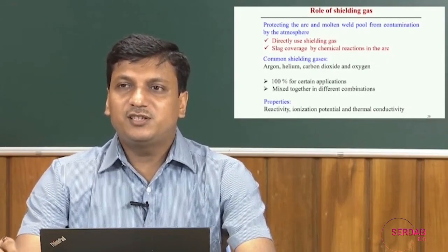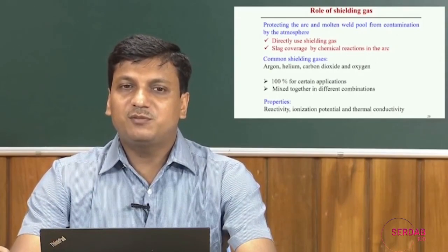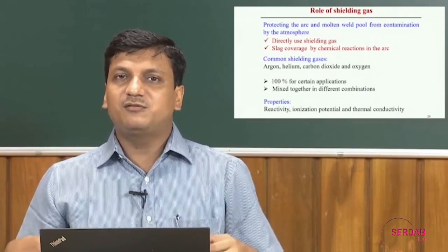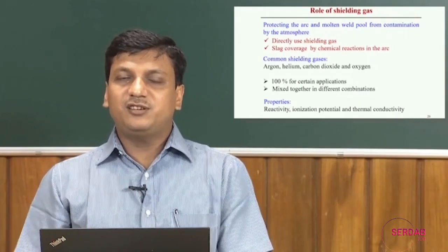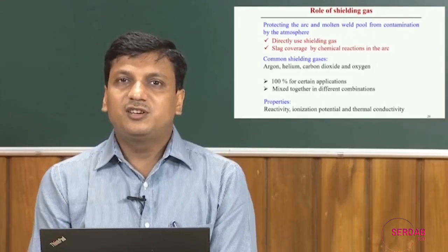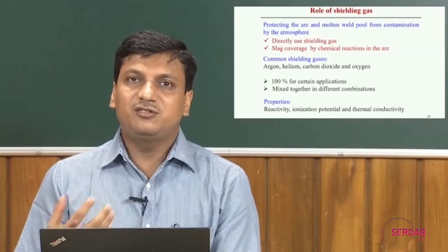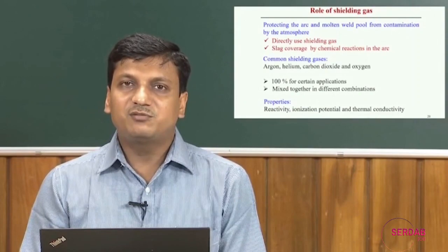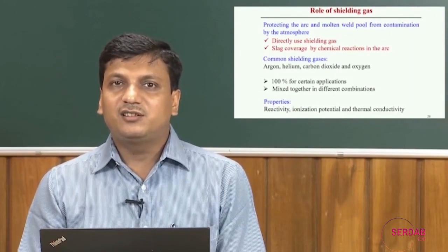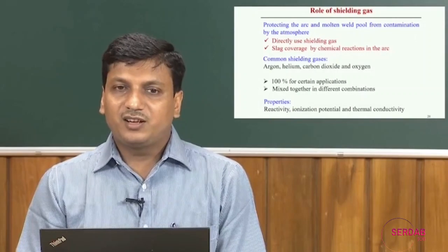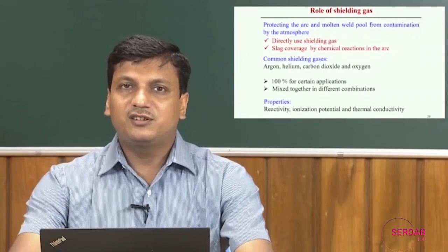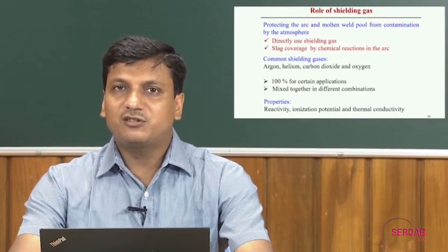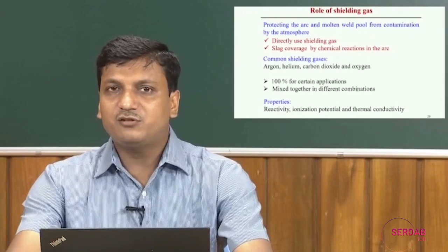But the basic principle of the shielding gas relates to reactivity. The shielding gas can be decided based on its reactivity with the molten pool in that high temperature environment, what the ionization potential of this type of shielding gas is, that means how easily it can be ionized or not, and what the thermal conductivity of this type of gas or of the workpiece material is.